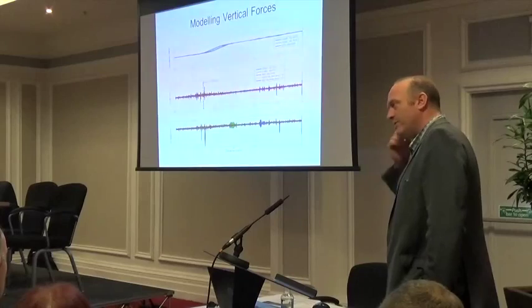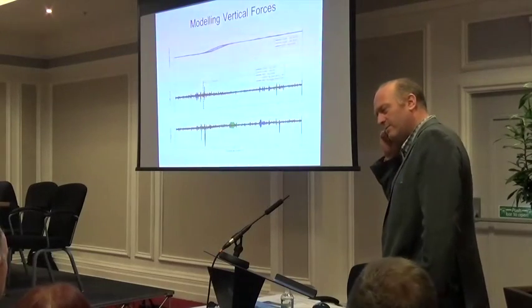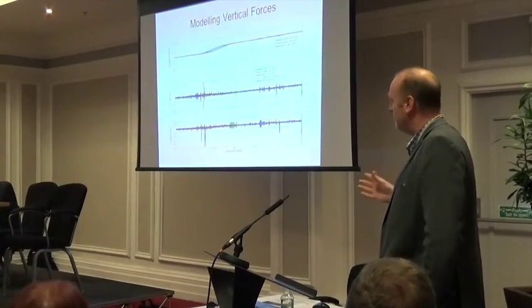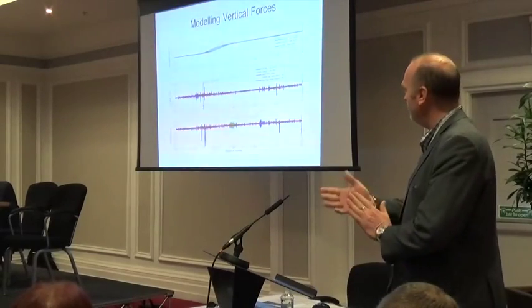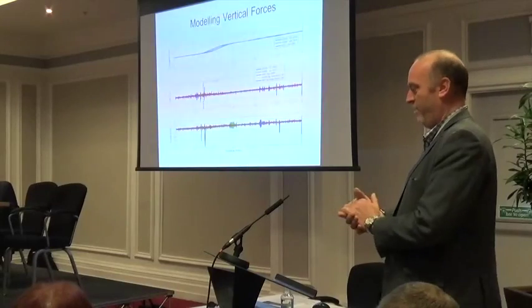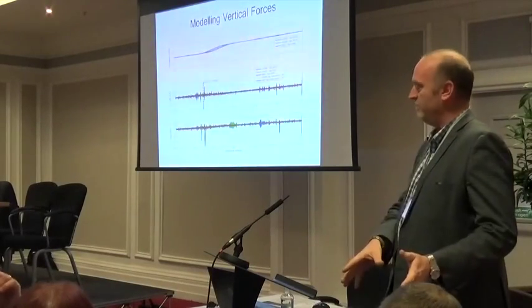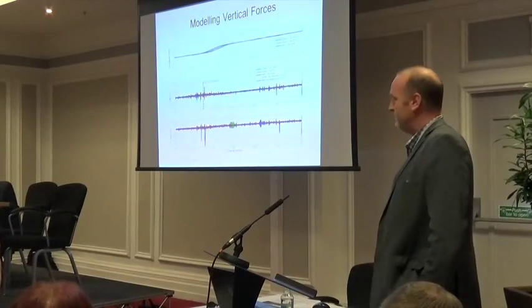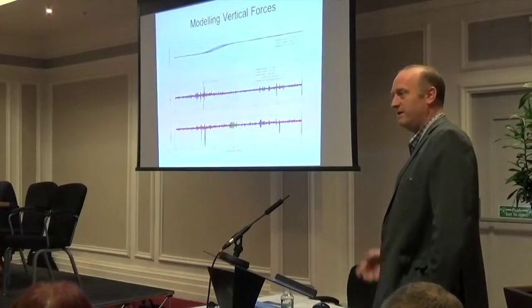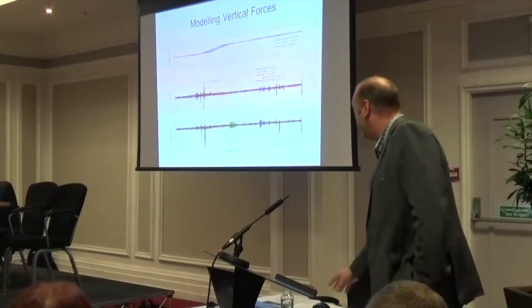So we're doing some work at the moment. I hope to have some load measuring wheel sets on one of our geometry or plain line pattern recognition vehicles to actually measure actual force in real time, and then compare that with track quality. Primarily I'm interested in the geometry, which perhaps some of it is around passenger comfort, actually picks up some of the higher forces that we may be seeing and certainly causes some of the deterioration and failures.